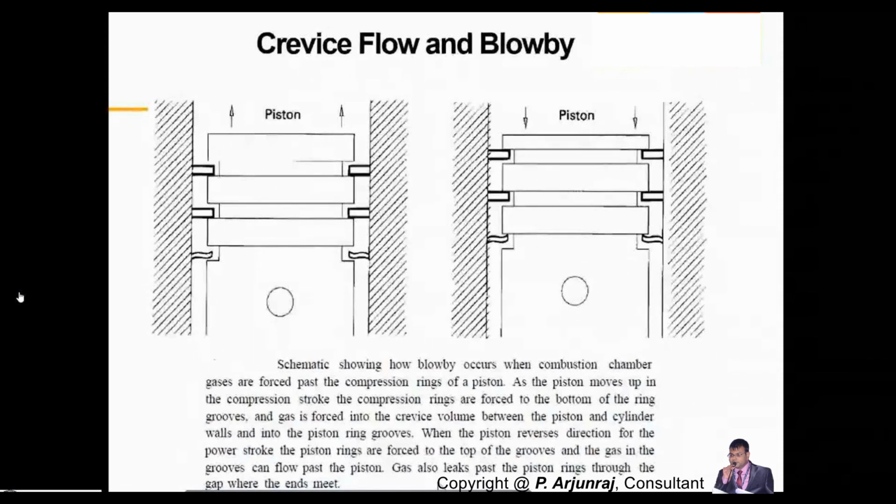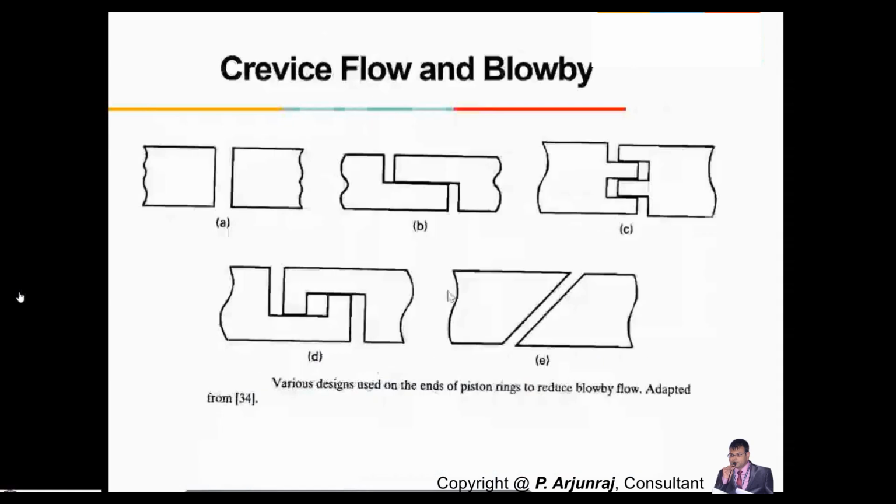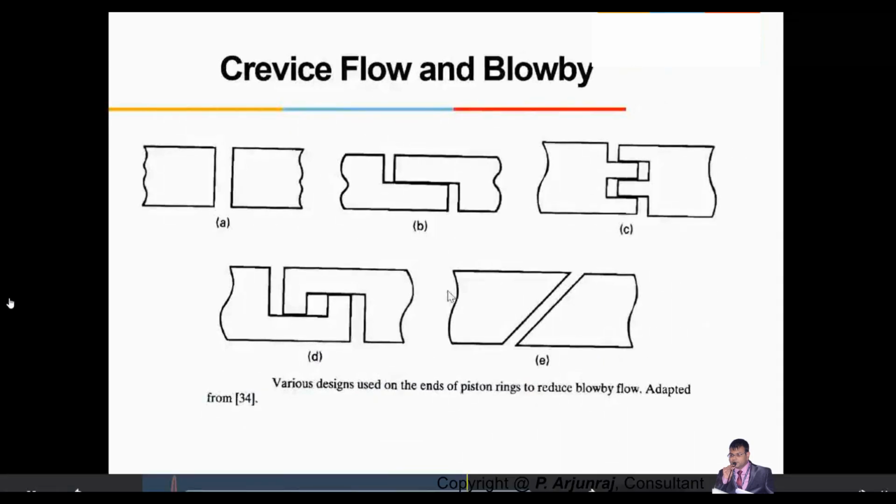Because when you have high blow-by, this will also affect your piston. The piston is basically the power producing part, right? This will affect your power. And sometimes higher blow-by will also damage your piston. So it's always important to design the combustion chamber considering less blow-by, providing the proper crevices to the wall so that the flow will be uniform and you can arrest the blow-by.